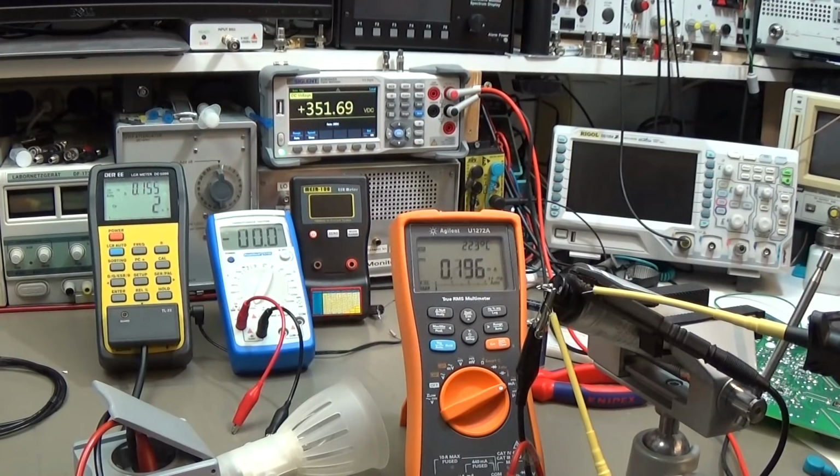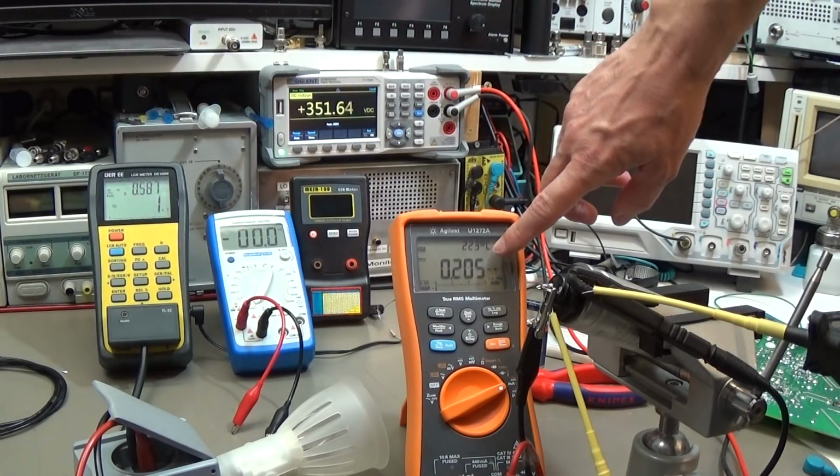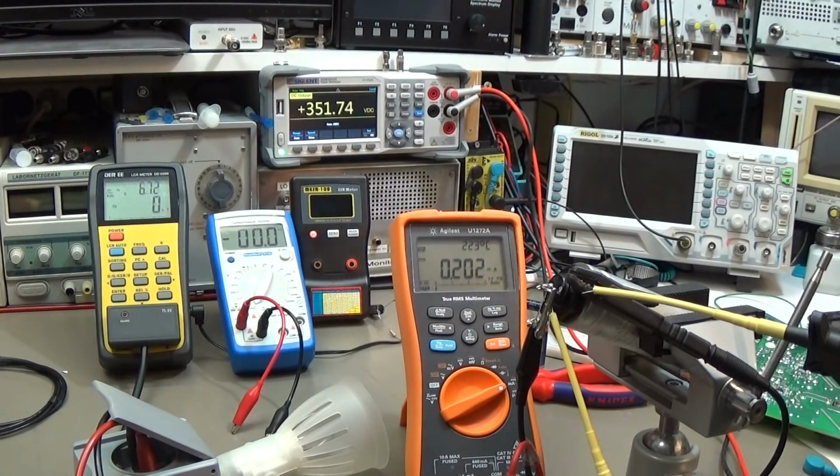And with these old figures, we are much better than what this table is telling us. And again, have a look how well our capacitor is doing. So we are under 200, I would say. So you see, it is really working up and down and back and forth, and that is clearly the indication that there is something going on in the capacitor, so that the capacitor really tries to follow up.